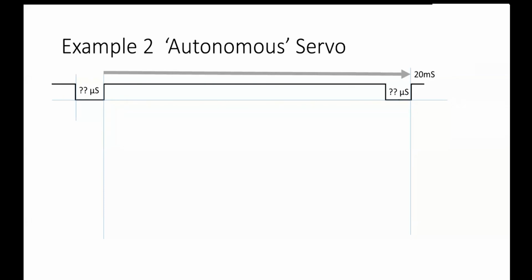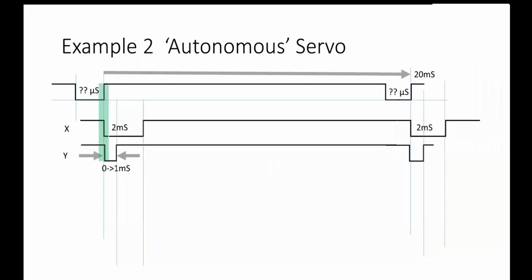What the size and shape of the pulse is, I don't care. As long as it repeats every 20 milliseconds, that's all I want. From it, I'm going to use it to trigger 2 other pulses on 2 other timers.